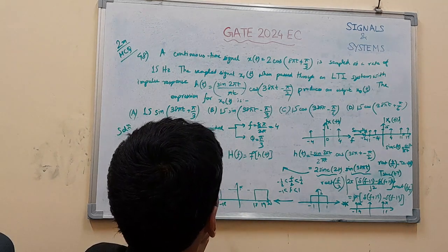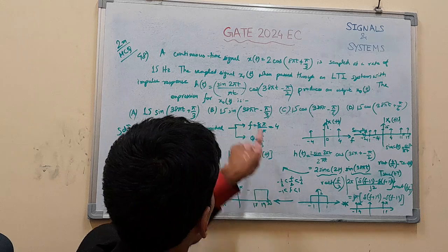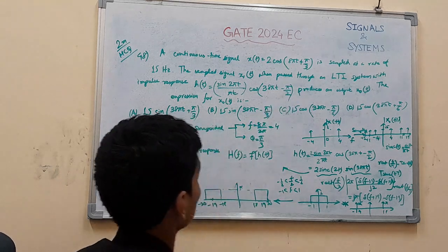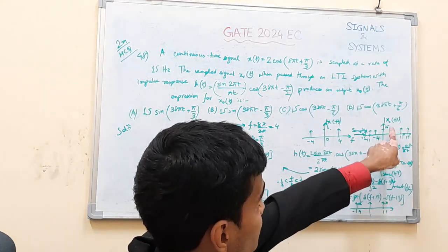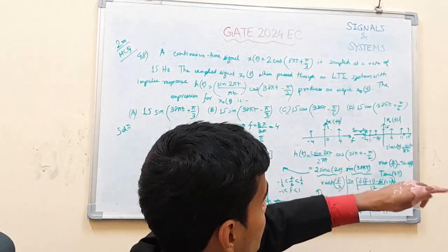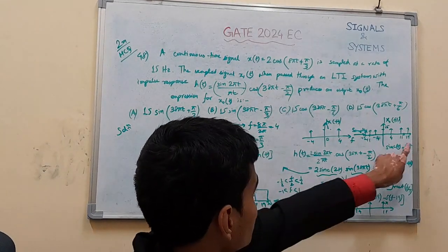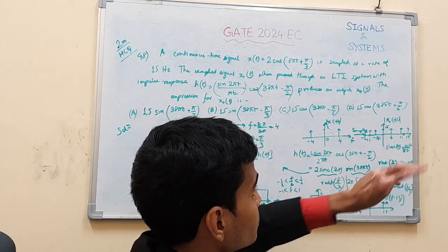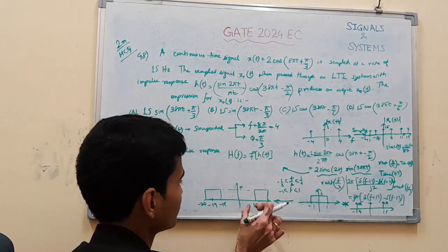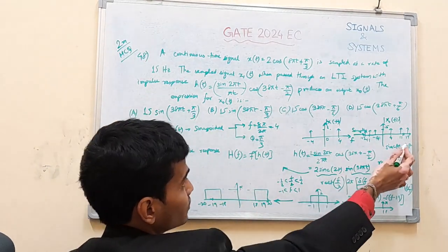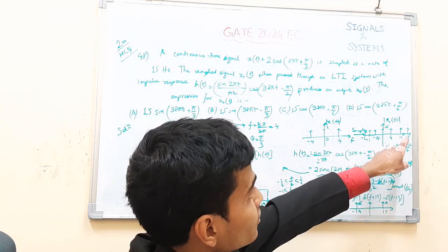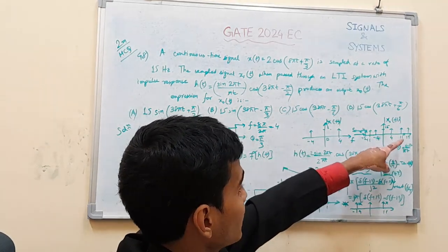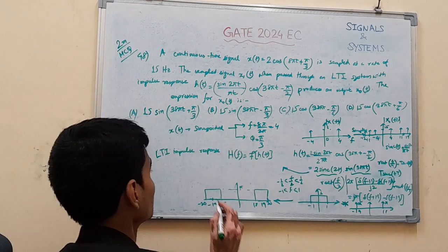Okay. Now there will be several frequencies in this sampled version of xs. The frequency that will come in this range will be only 19, because the remaining frequencies will get rejected, because they will not lie in this band. So only the component with frequency 19, that is an angular frequency of 19 times 2 pi, that is 38 pi, will pass through.